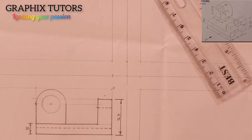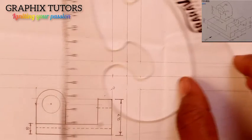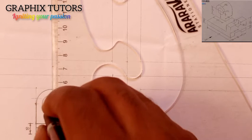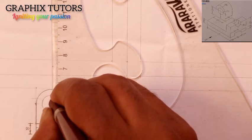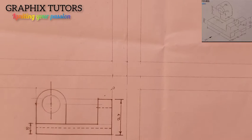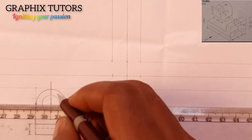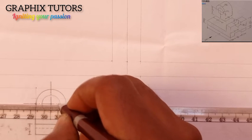Is that taken? So we know that this is a center line here. This is a center line because it's a circle, a symmetrical object. So I'll use one long one, a short one, long one, a short one, and long one here, right? And I'm going to do it here too. At this point, I'll do one long, short, long, short, long.